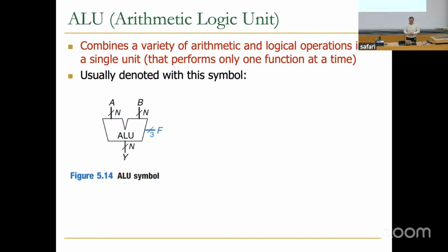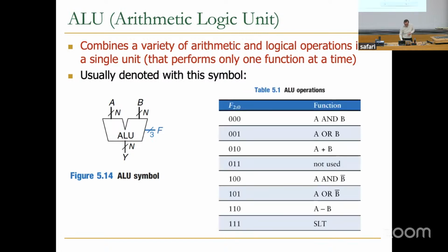And to be able to distinguish between those functions, you need kind of a decoder, right? F specifies your function in 3 bits, and you need to decode which function you're actually going to execute by having a decoder internal. And you will see that soon. But assuming that this is the specification of the function, someone needs to specify this, of course.